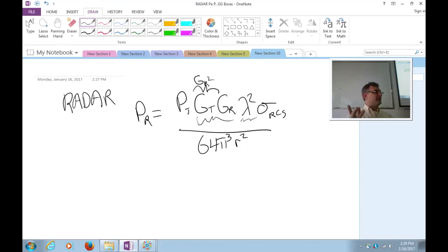And this explains why radars tend to operate at really high frequencies. Maritime radars tend to be around 8 gigahertz, higher than you would do cellular communications, because you have the freedom to point both the transmitter and the receiver. And of course, there's all the different military and aviation radars out there that generally inhabit the microwave or millimeter wave spectrum.